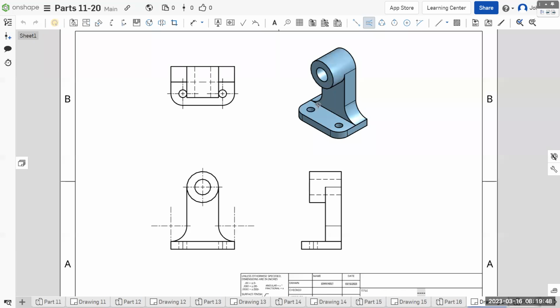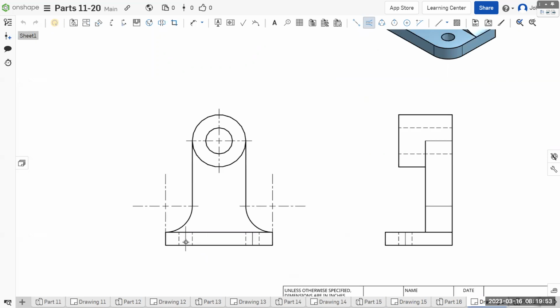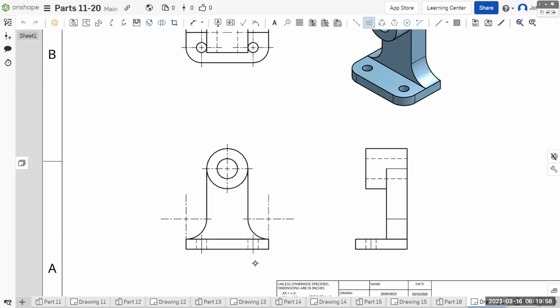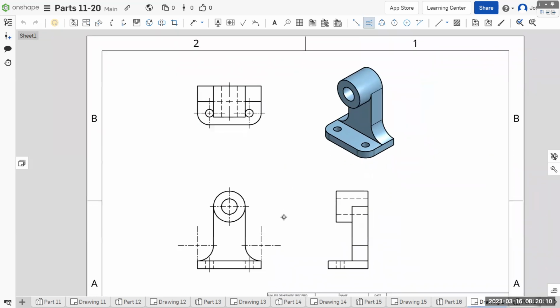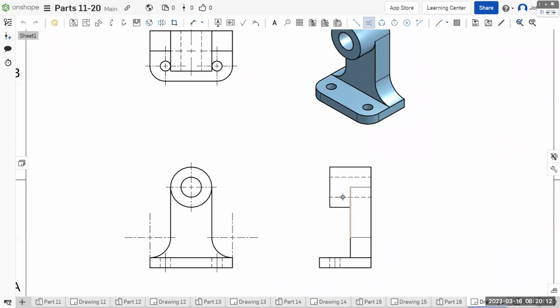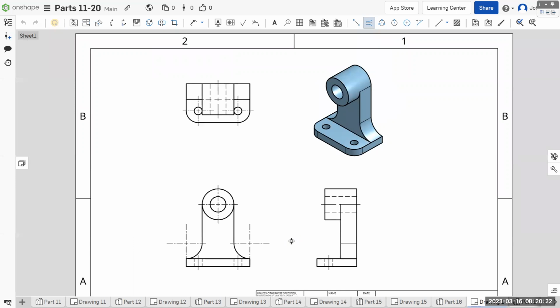Where do things go all the way through? Well, these tiny holes go all the way through. We can go center there, and you can see how it's sticking out, shows the viewer that it goes all the way through. And on the top view, things that go all the way through are just this. And on the right side, things that go all the way through are this, which is that top horizontal hole. And this goes all the way through between there and there. That's it for through lines.